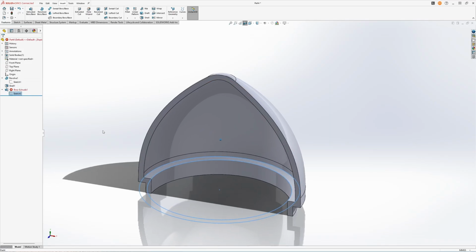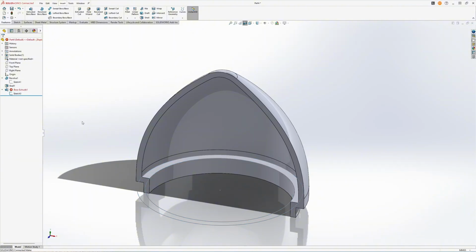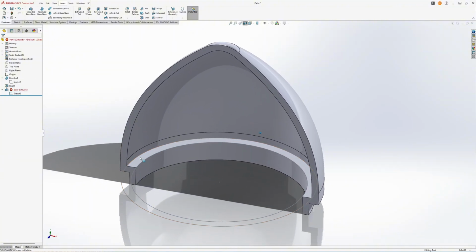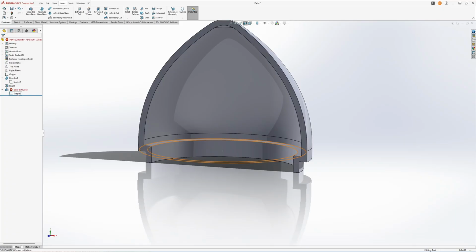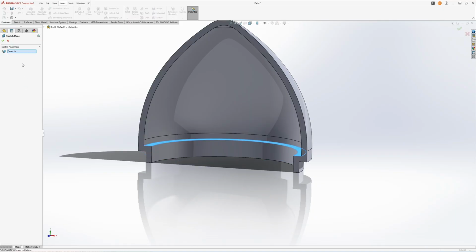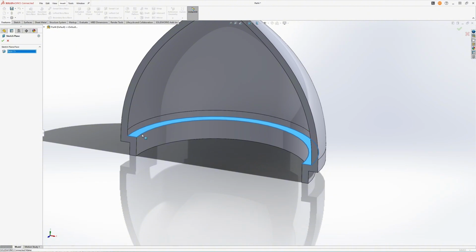So it looks like our drawing itself is fine. It just doesn't know where to start the drawing. So you can see here, could not find end face for feature. So to fix that, we just right click here and we click the sketch plane. And we say here, actually, let me correct myself.